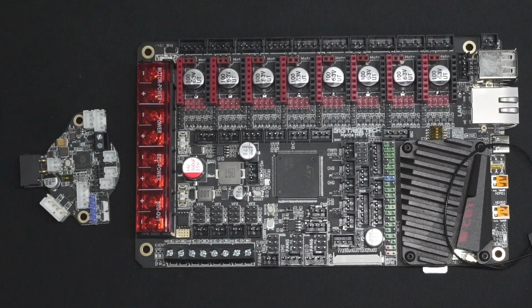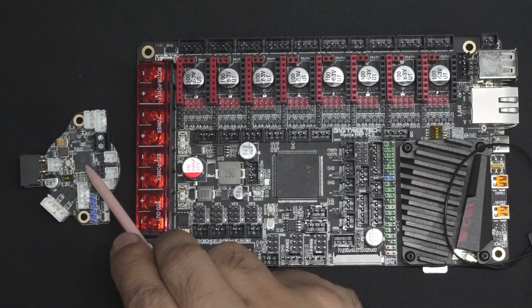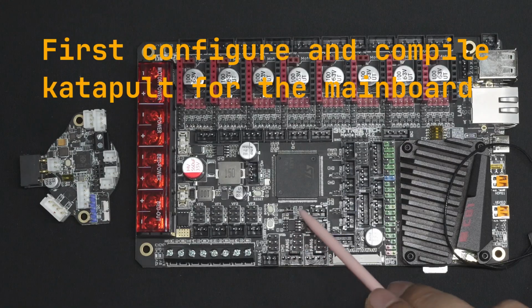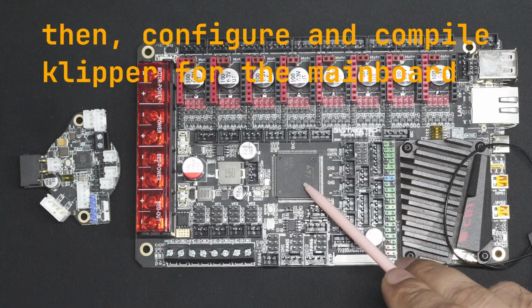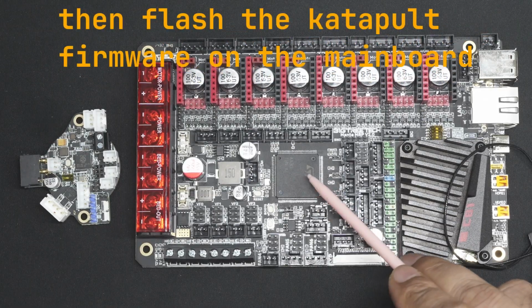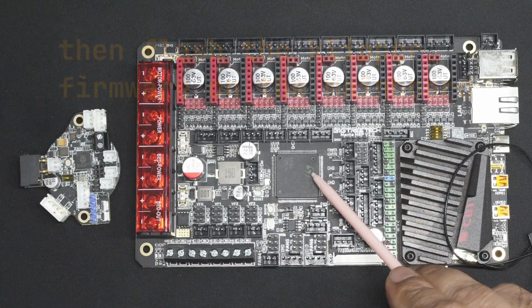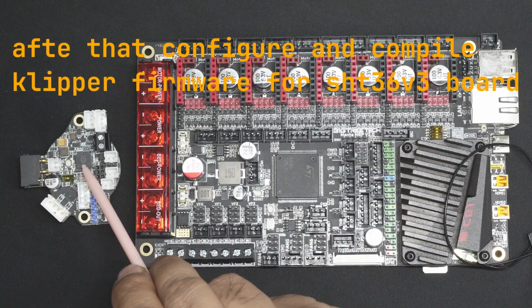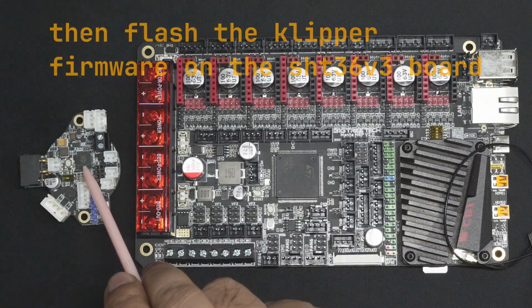To get the CAN bus working, the mainboard STM controller and the RP2040 on the SHT36 must have the Katapult CAN bootloader installed. So I'll be following these steps. First, configure and compile Katapult for the mainboard STM microcontroller. Then configure and compile Klipper for the mainboard. Then flash the Katapult firmware on the mainboard. Then flash the Klipper firmware on the mainboard. After that, configure and compile Klipper firmware for the RP2040 microcontroller on the SHT36 board, and then flash the Klipper firmware on this board.